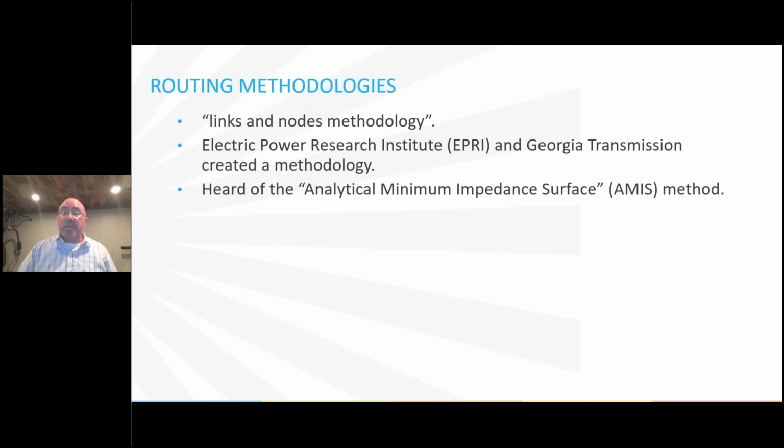So the method I will be discussing is referred to as the links and nodes methodology. It's a methodology that we've been working with for a while and has worked well for us. It relies on GIS data collection, digitization, ranking, and expert judgment. You can apply weighting if you need.